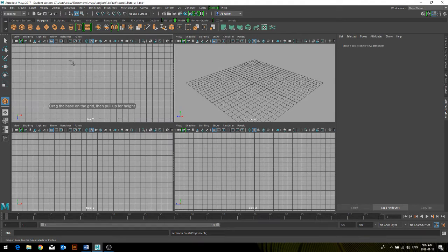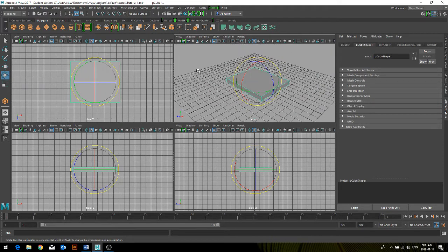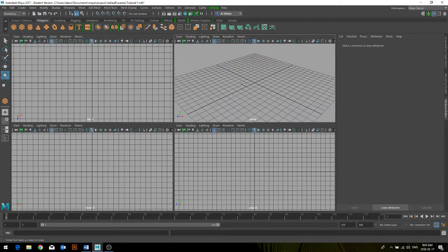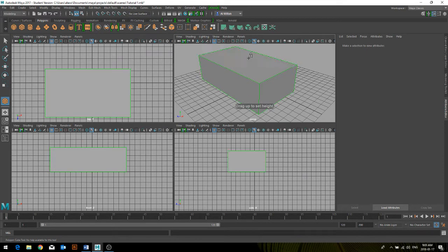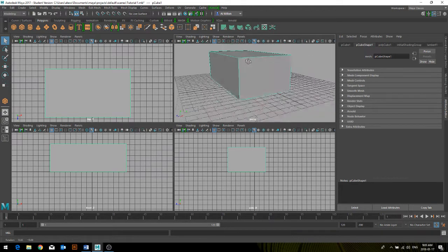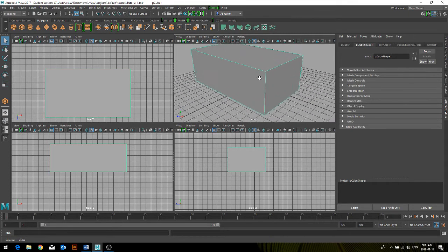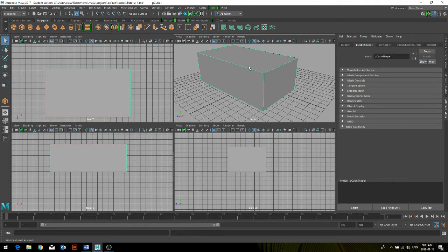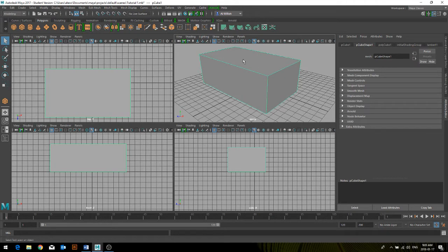and just for this introduction, I'm going to take the cube, and we'll make a better cube than that. Sorry. There we go. And so once you have your basic primitive, if you hold Alt, you can rotate around by left-clicking. If you right-click, you can basically zoom in and out, and if you hit the central scrolling wheel, you pan.